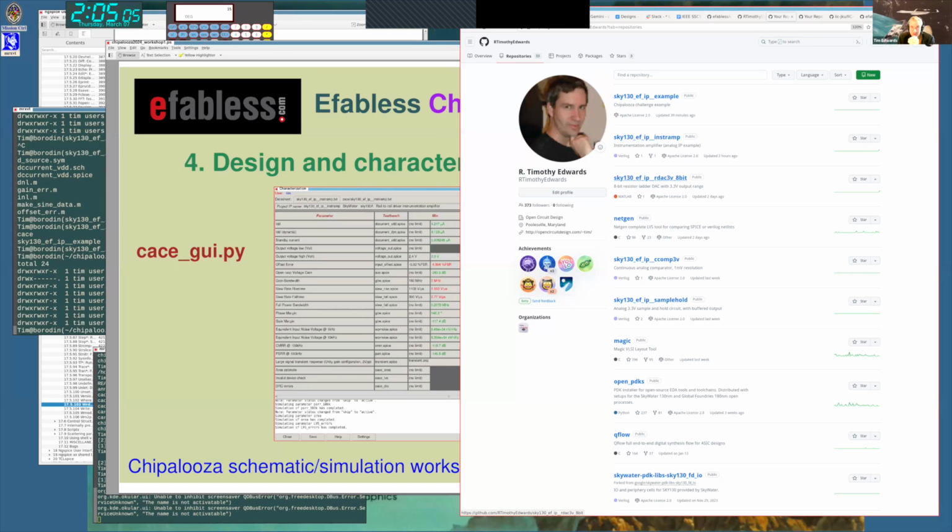I declare the analog inputs as real variables in Verilog, and then I just say output is equal to 1,000 times input P minus input N. So it's not trying to capture any of the analog artifacts, but just says, all right, this is how an amplifier kind of works if you treat it as an ideal thing. And that's enough to give you functional verification inside of a larger system like an SoC.